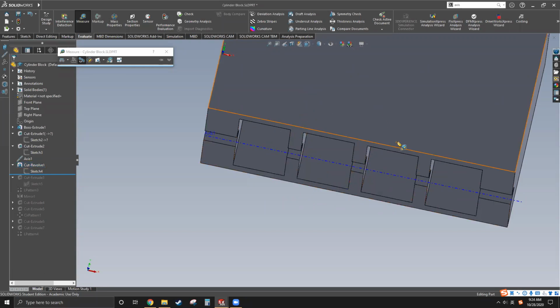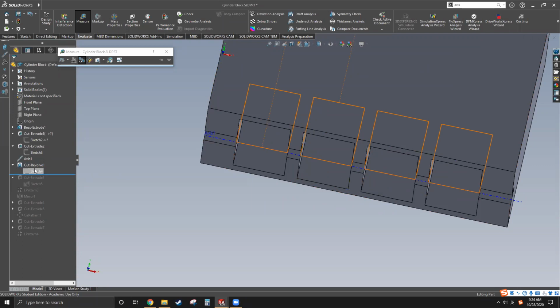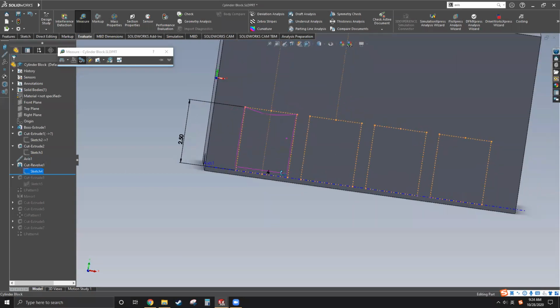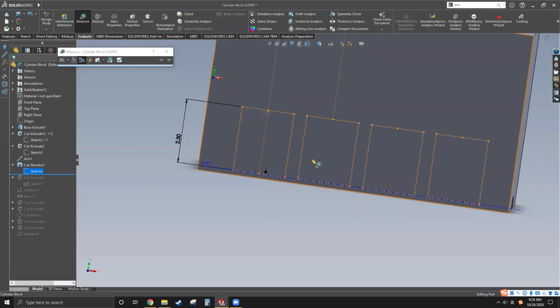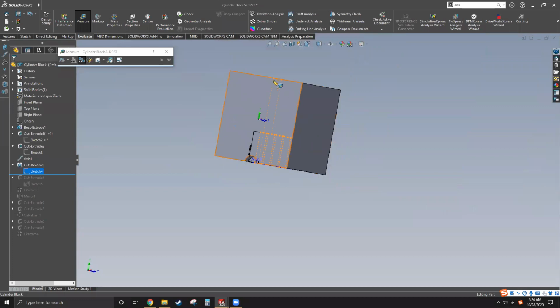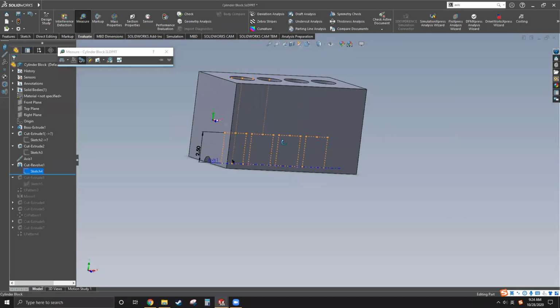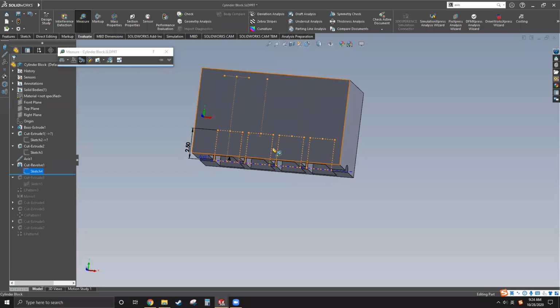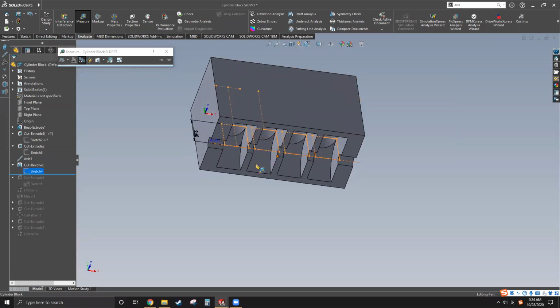What I did after the axis, this is the step right after the axis. The axis is right here, and this step is creating 4 rectangular shape sketches in the middle plane. And if you don't have a middle plane, you must generate a middle plane. And after you have these 4 sketches, you cut those with respect to the center axis that you just generated.